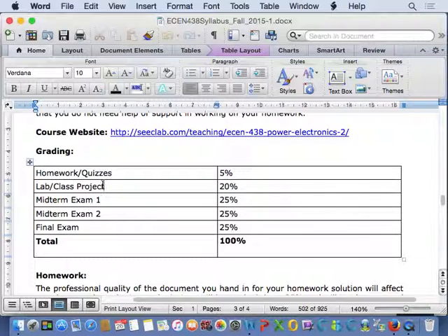The fire alarm is a very important part of the building, right? You would not want the fire alarm to go down. So in that case, you would not depend on a generator to start up and switch the power supply from the utility to the generator to supply the building. You would have a UPS. A UPS is an electronic backup power supply. Electronics are much faster than mechanical systems, so a UPS can start in split seconds, and there are many different types of UPSs.